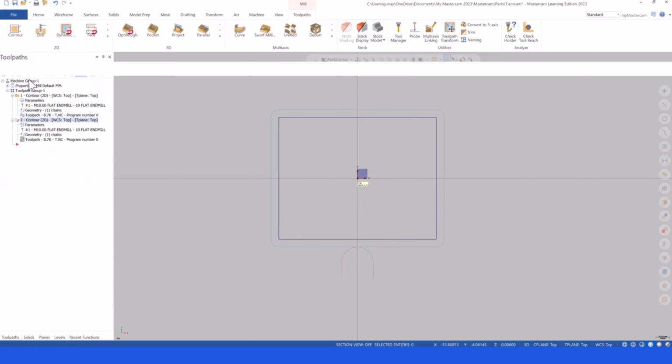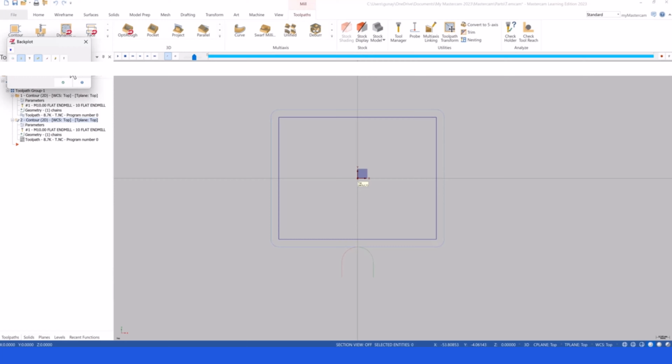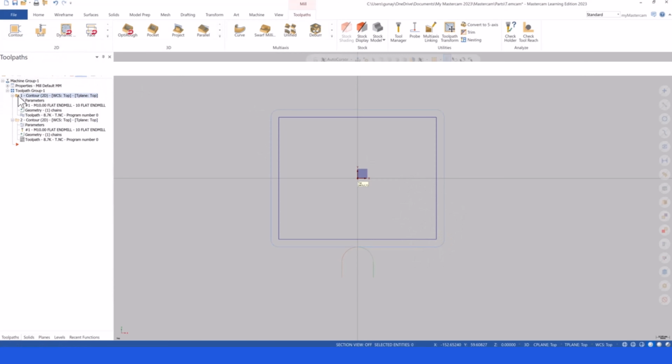Okay, and then when we turn to here, this is actually conventional machining. We are rotating like this. This is my tool, and then we're gonna start from the minimum to maximum. So this is the up milling, minimum to maximum, minimum to maximum, and then we're gonna use conventional or up milling here. So when we turn to here, actually this one is climb milling.